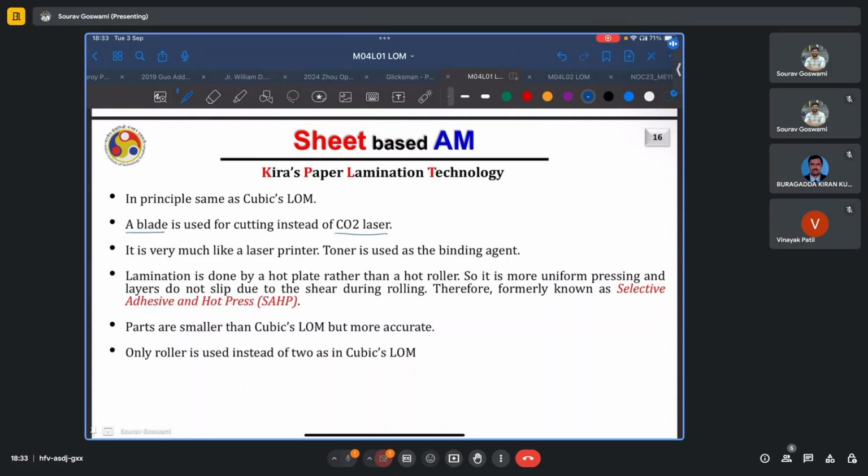What difference this introduces, apart from the very physics of the problem, is also the omnidirectionality. When you have a layer, this is your contour. If you are scanning it via a laser, it does not really matter whether I go this way, or do I scan half, then I start here again and scan the other half, or whichever way I go. Because the laser beam is omnidirectional, its properties do not really depend on the direction of travel or traversal.